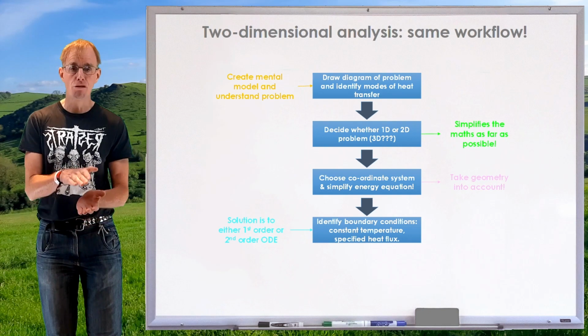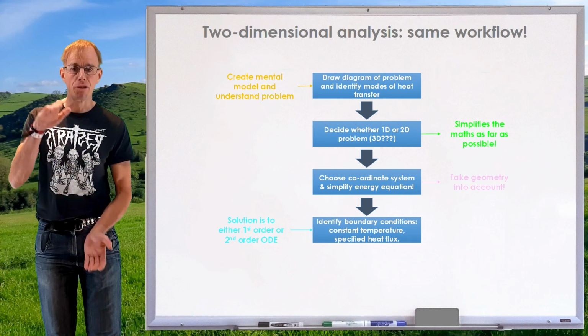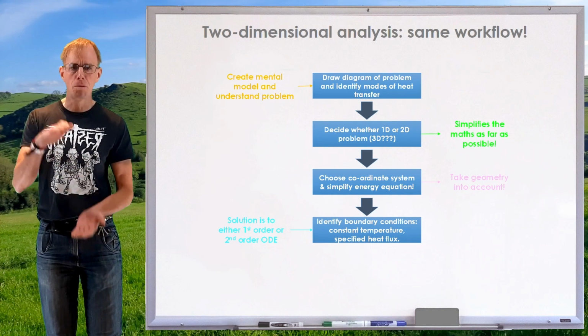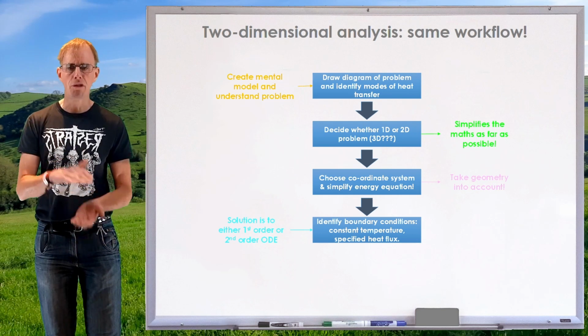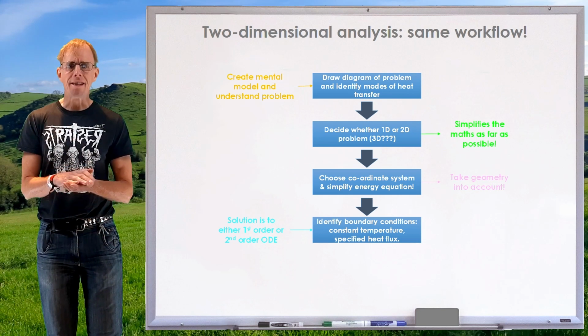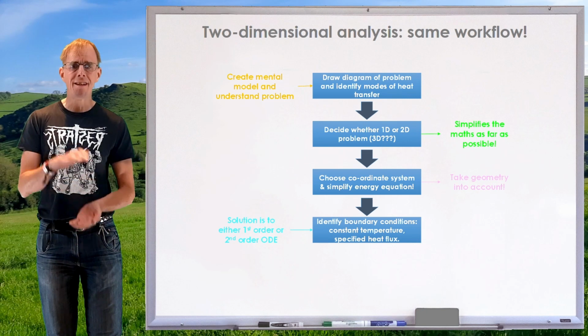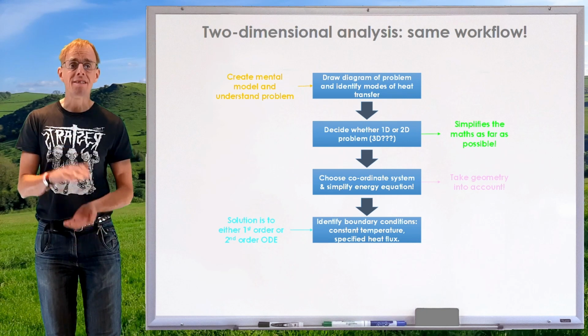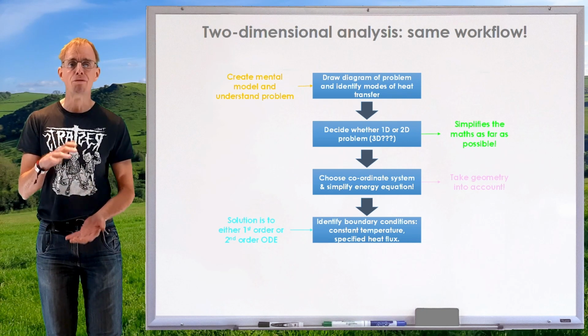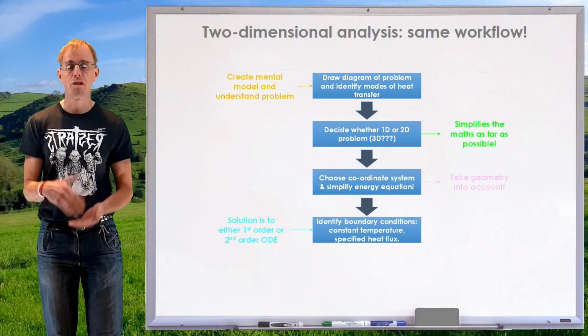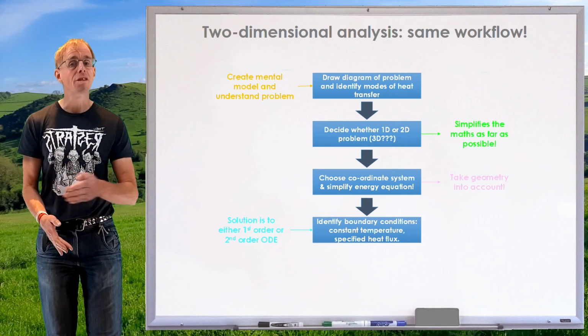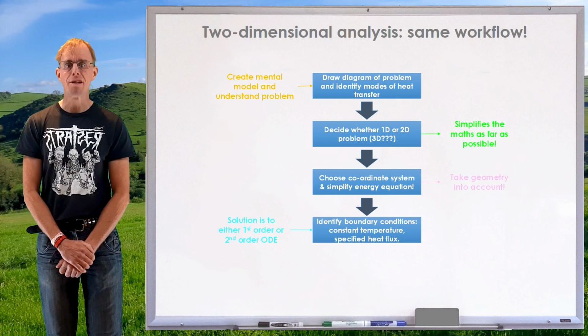Remembering that convective heat transfer is going to be lost from the surfaces, and we're going to say that is vertically up or vertically down from a horizontal surface, and that the internal temperature gradient in the material is unlikely to exist in that direction if you've got a very, very good conductor of heat. For example, a metal. It will exist along the length of the extrudate or the product.